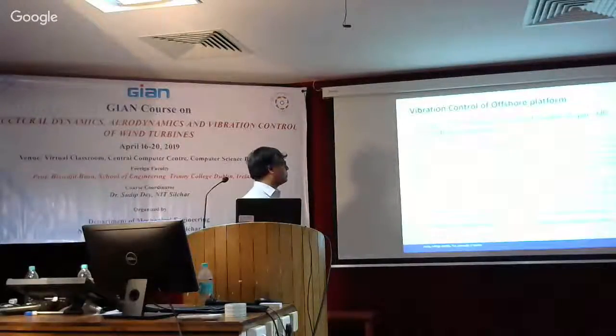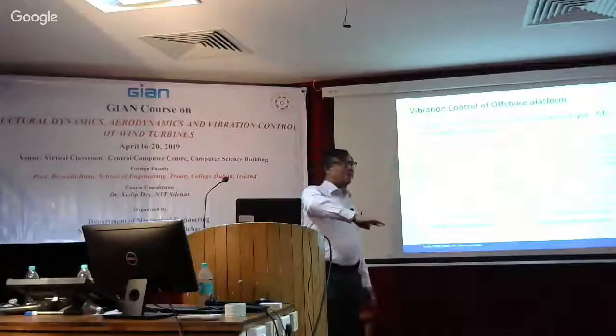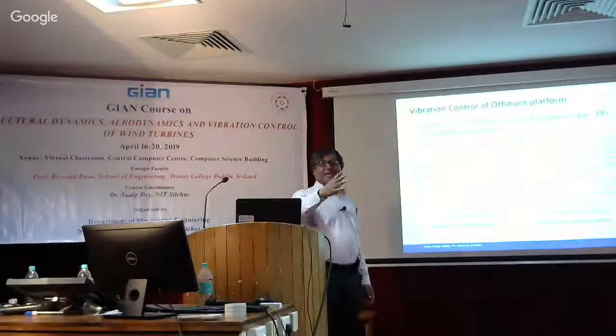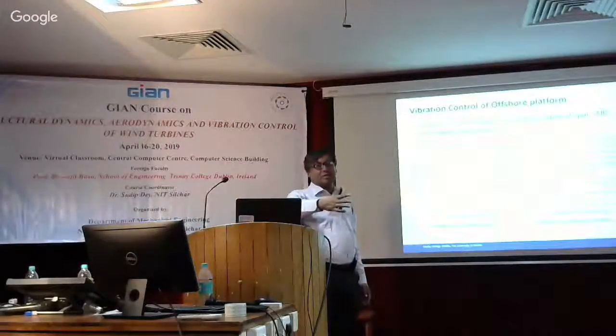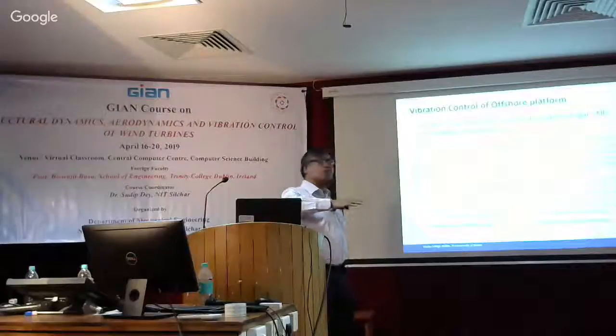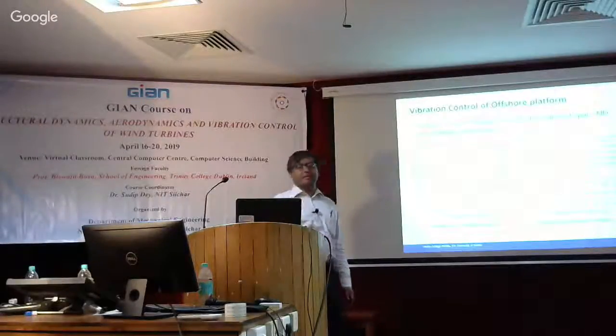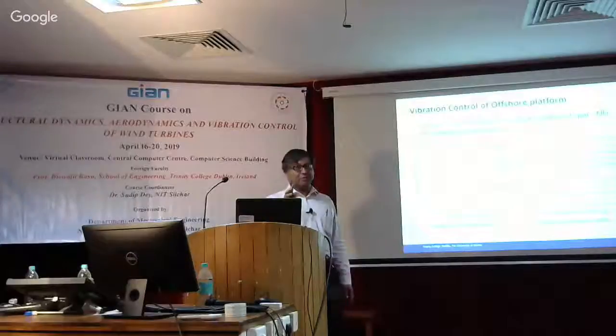These are some of the control results where we have optimized the position of the TMD and looked at the vertical position of the TMD along the spar and looked at the reduction in the vibration, both maximum and RMS values, and it works very well in terms of control of the vertical vibration, vessel motion. Also, what we found is that the motion of the platform doesn't induce much vibration of the blade because the blade frequency is far away from the frequency of motion of the platform. But obviously, we haven't looked into any instability or coupling instabilities. That can happen because that's what has been observed.